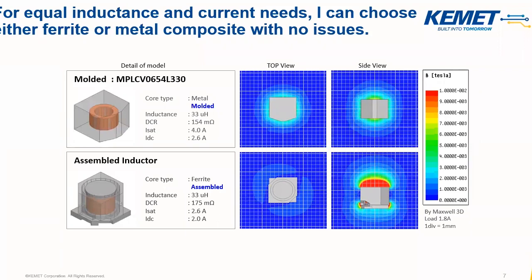Okay, thanks, Alex. And Peter, I think you've seen a case out in the field where somebody chose one of these assembled type inductors without necessarily considering the flux leakage here, and that kind of got them in trouble with some induced eddy currents, right? Absolutely, and we see this happen periodically. So a lot of your ferrite inductors are inherently unshielded. There's an exposed air gap in them, and magnetic flux can leak out of that air gap. The picture here sort of illustrates that.